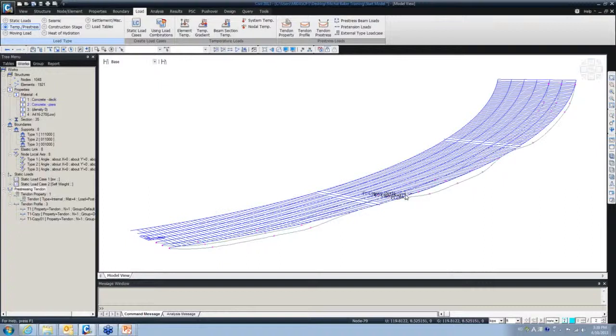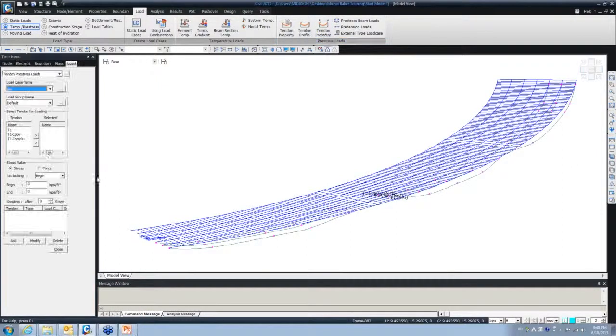So I just want to show you what's going on there, and keep moving on, and then show you the other options. Later on, when you want to apply the pre-stressing tendons, you can go with the tendon pre-stress and select, for example, all three of them, and add them to the right box, which is the selected box. And for the post-tensioning, you have options. Post-tension can be from one end, from the beginning, from the end, or from both ends. Definitely, when you are post-tensioning from both sides, technically you're gonna have less friction loss because of the shape of the tendon profiles.